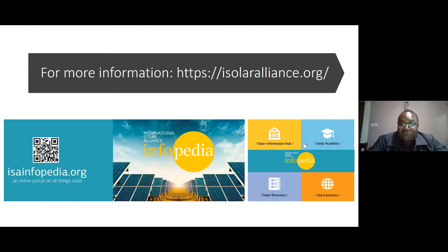And of course, roofs are also good accumulators of temperature. So one of the ways to deal with this during installation is to have some clearance, with the solar PV slightly elevated above the roof. This is one of the methods that are being used. And of course, you use natural air currents to provide some cooling effect during the day.